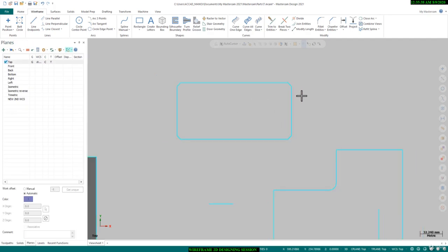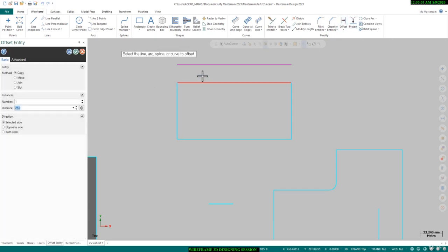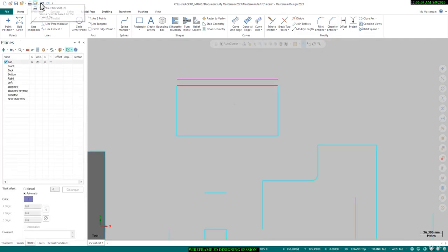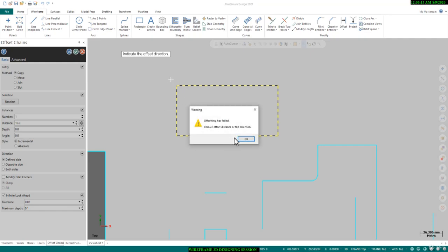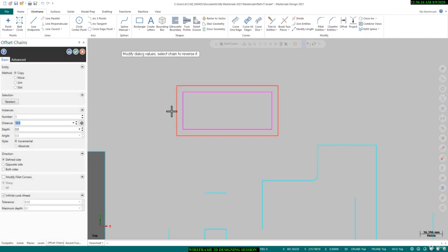Okay, so the next very useful command is offset command. Suppose you have to offset, I will click here undo. So now we will offset it. Offset this line, suppose we have to offset from here to here, and we will give 10 mm of value from here to here. Okay, and after that suppose you have to offset it from all over the area. Okay, and then okay, so I will give the radius value, suppose 5 mm.